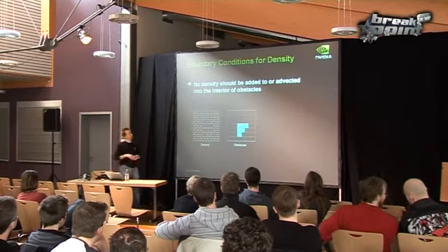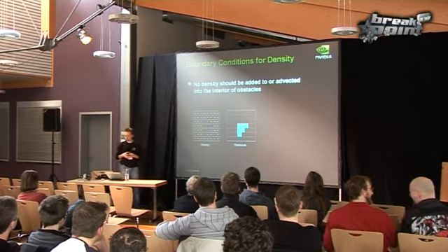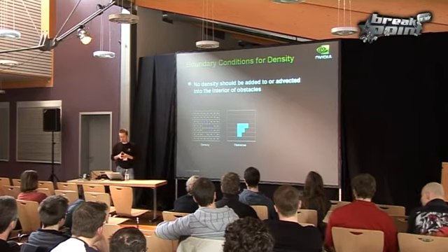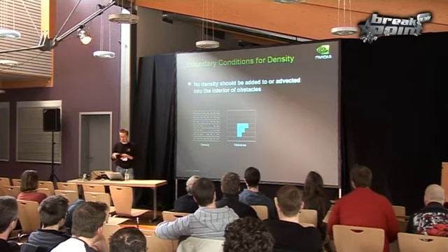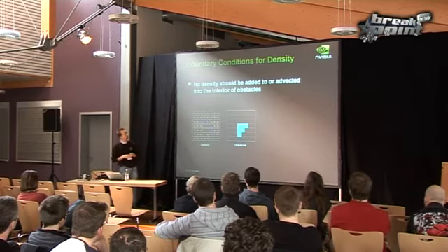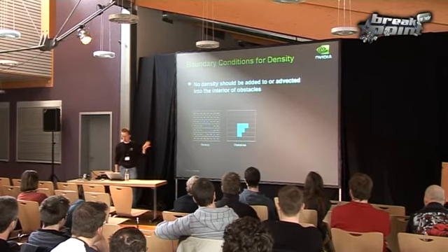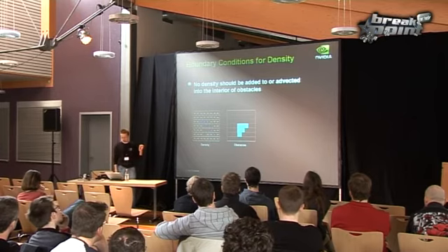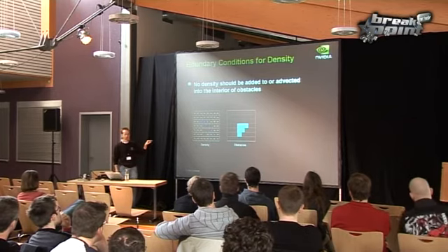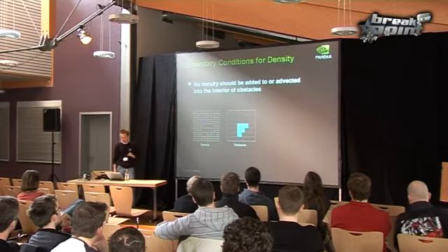In order to enforce these conditions, after the advection steps in the projection step, we basically need to satisfy them. Satisfying the conditions for density is actually pretty simple. We need to make sure that we do not allow density to be present within the obstacles, so we need to remove density from those cells.